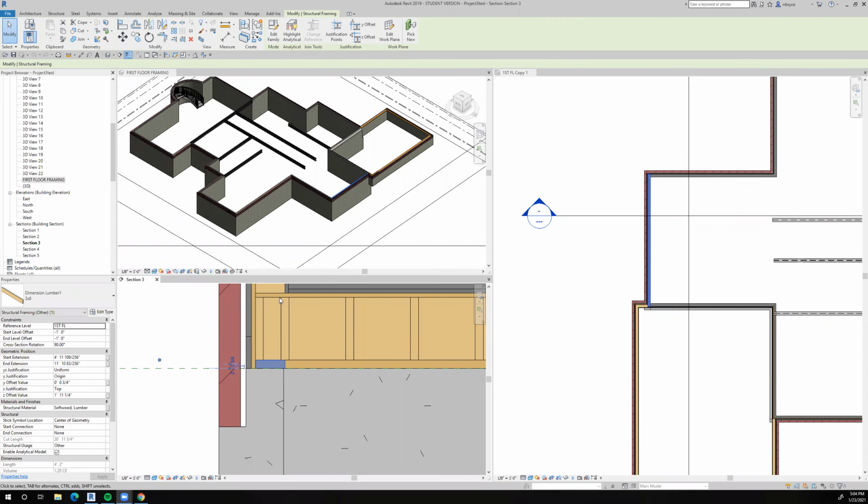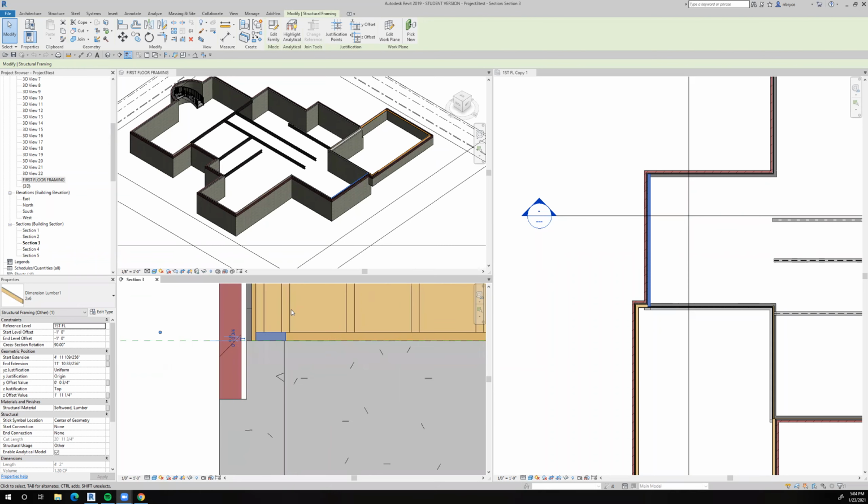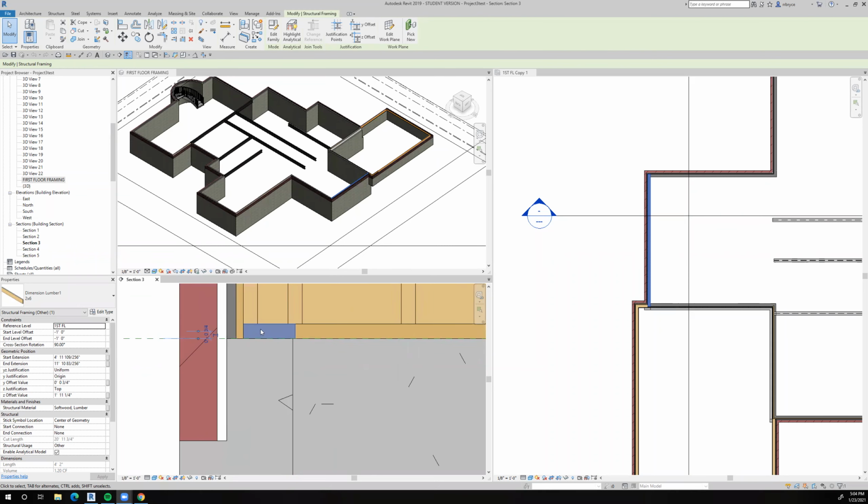We've put in our floor joist. Now, between the top of the basement wall and the bottom of the floor joist, we have to put in a 2x6 sill plate all the way around the perimeter of the basement wall, because the floor joists don't sit right on top of the basement wall. They sit on a sill plate.